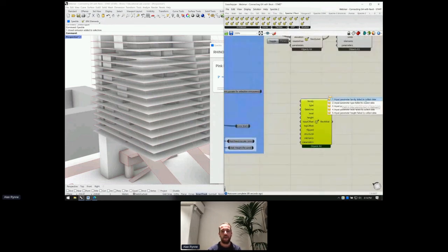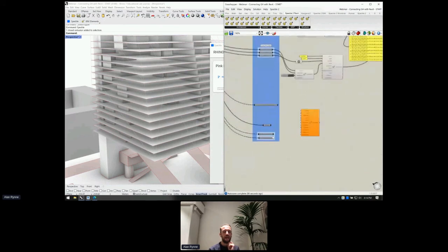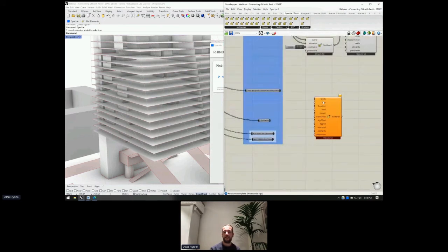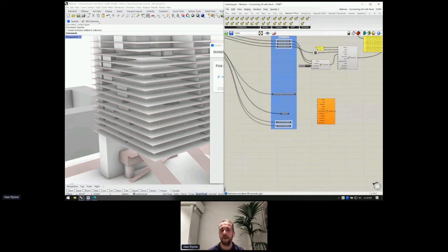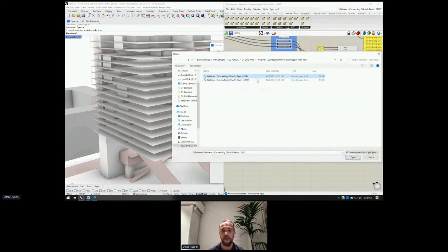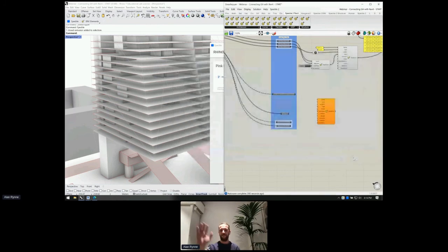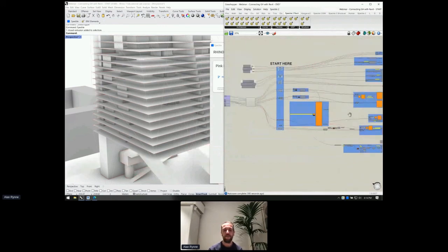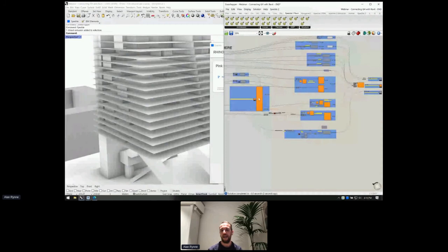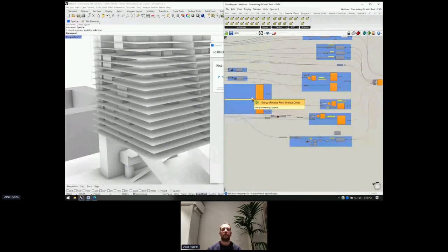So if we chose create a wall by curve and height, then we would have to specify the family, the type family, the baseline, the level, and the height that we want these walls to be at. In this case, I'm just gonna skip directly because we're running quite late. I'm gonna cheat. I'm gonna pop open the end file, which I prepared specifically for this purpose, which is basically the same file, but already properly finished. And I'm gonna walk you through the interesting part.